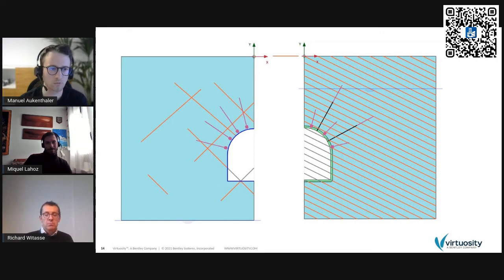I could talk about shotcrete and steel arches, which are maybe the two most relevant types of support one could think of. There is concrete as well for the final lining, but I would say shotcrete and steel arches, which can be applied either on plate elements, as you could see, the blue lines on the left-hand side figure, or as a solid, as a continuum element, which is the green volume on the right-hand side.